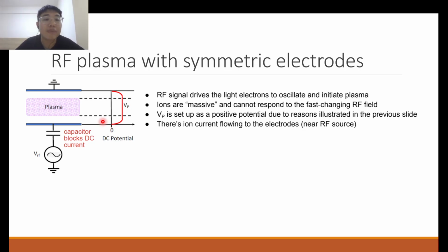And so we actually notice something interesting over here. We notice that there is an electric field, a potential drop at the electrodes, even though there's no DC bias. We only have an RF bias that has a time-averaged potential of 0 volts, because if you do a time average of the positive and negative alternation, you get 0. However, there still exists an electric field, a potential drop at the electrode surface, and that's very important because when